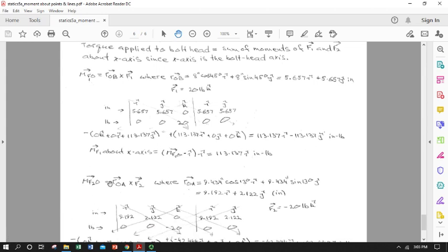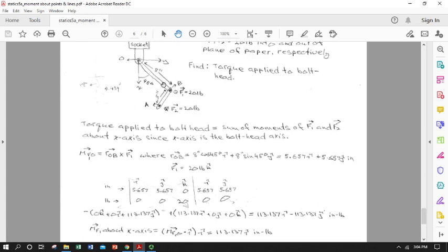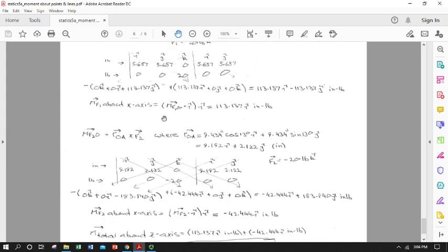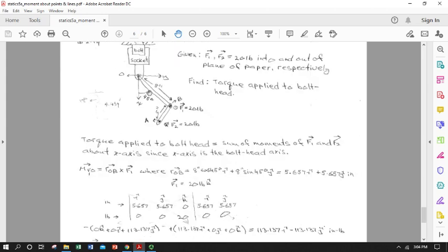So now we'll look at A. I had to do a little bit more geometry to get this distance. I used the fact that this little segment AB is perpendicular to the 8 inch. And so I went from point B, and then I subtracted back the amount that would be given by this other right triangle that you can construct. So there's a lot of geometry and trig in statics, just figuring out where things are and which way they're pointing.